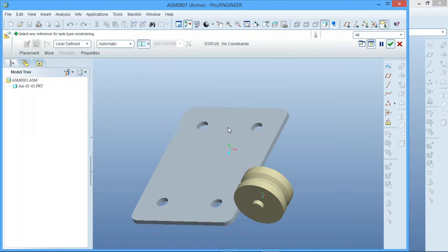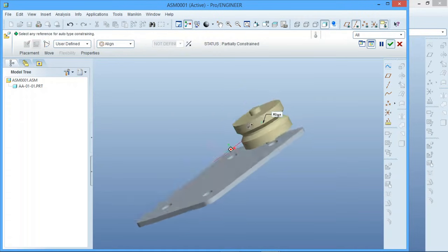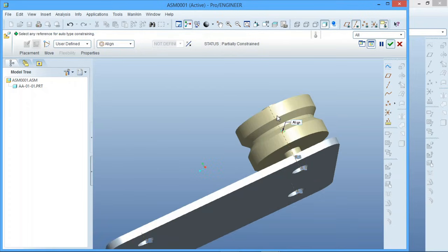Okay, so one of our other assembly features is if you use your shafts, any round cutout, any round shaft should automatically have an axis. So the simplest way to align any round part is to click on the axis and then click on the other axis, and then as you can see it's assembled it.